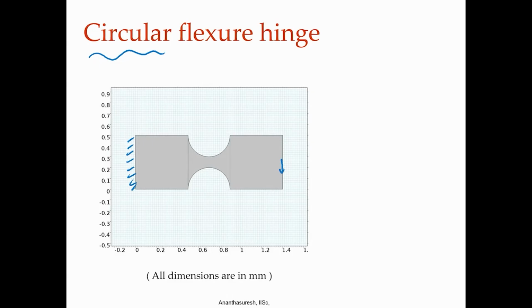When you do finite element analysis, you have to choose the type of element. Choosing the type of element merely means that you are defining how you interpolate the displacements or other quantities within the element, because every element will have a certain number of nodes and only at the nodes we compute the displacement. Inside that element, how do you know? We use the shape functions.